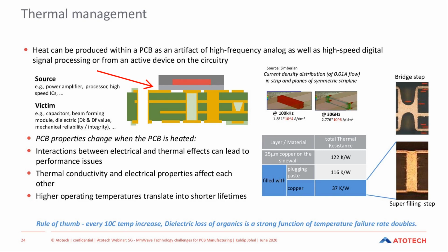One really important aspect to note is that as signals are generating heat and moving faster, we will see the heat is focused and concentrated in the high current density areas of the trace. This is multiplying the amount of current that is subjected to those particular areas of the trace, which is then making thermal heat dissipation much worse, because now you've reduced the trace area considerably compared to where the thermal heat mass would be moving through the whole trace.